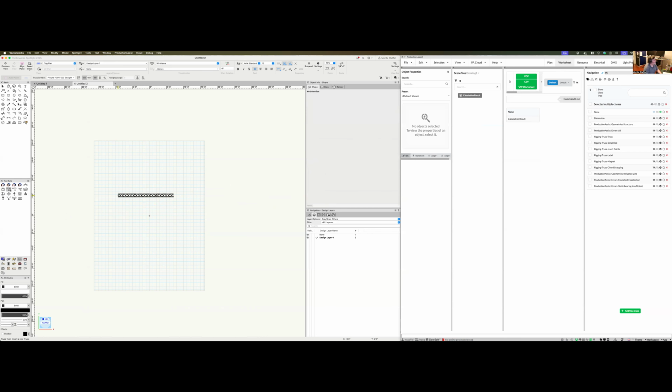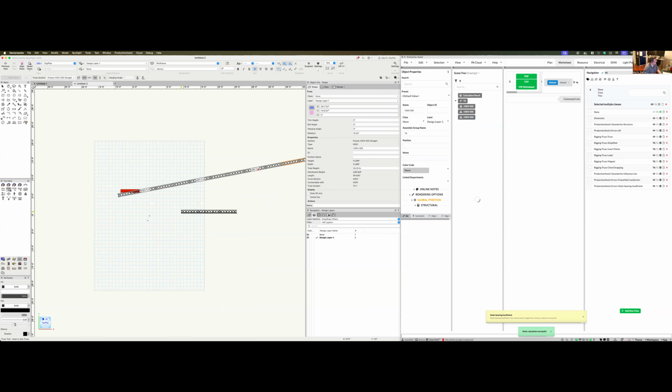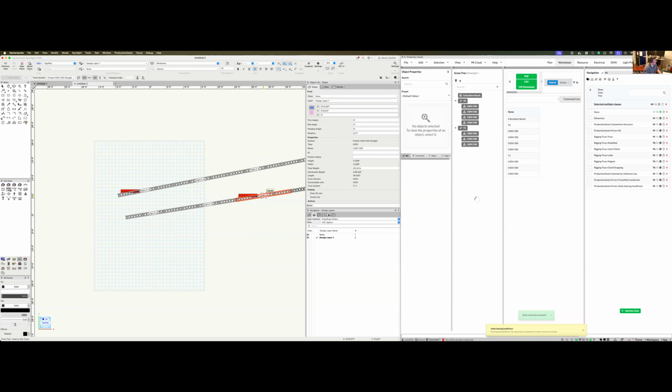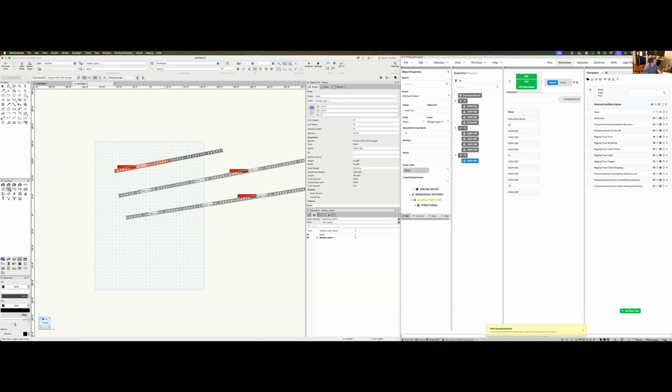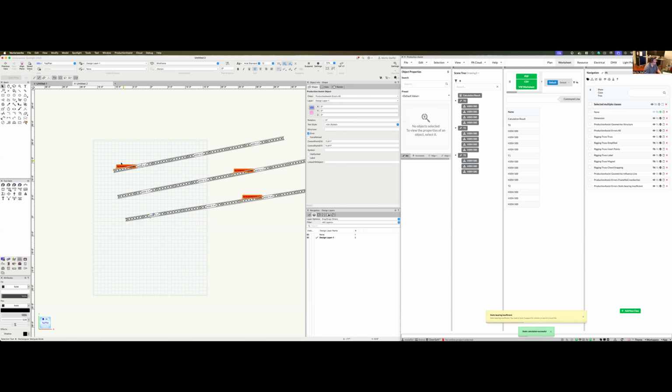Now let's get hands-on. We'll begin by inserting trusses and hoists, and then explore how Production Assist calculates load distributions in real time. Start with a clean drawing and use the dedicated truss tools to insert your first truss. Production Assist immediately reads this element, checking for common issues, like missing support. You may see an initial error message, prompting you to add support.